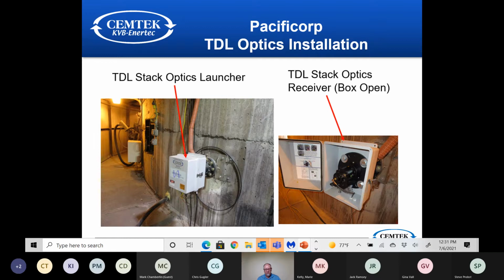In the trial that we were doing, where we're up on a stack matched up against a CEMS that we supplied years ago, we're measuring CO, CO2, NH3, and O2 with the TDL, and we're measuring NO, NO2, NH3, and SO2 with the UV DOAS. There was moisture that had accumulated on the optics from a very cold day, because this was just a temporary trial setup. Even though the lens was almost completely fogged up, we were still passing daily calibrations, and they were doing a RATA, and we were passing the RATA.